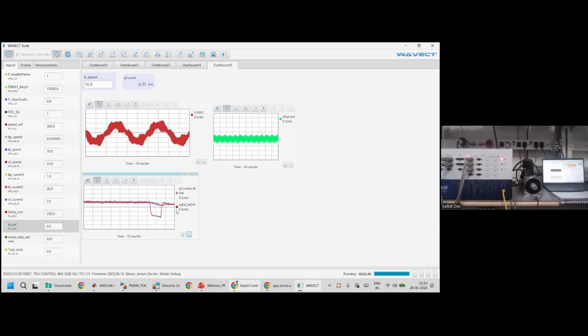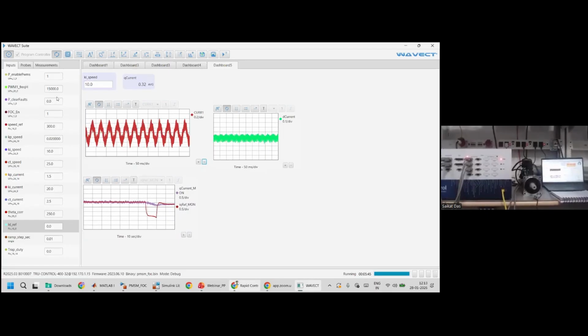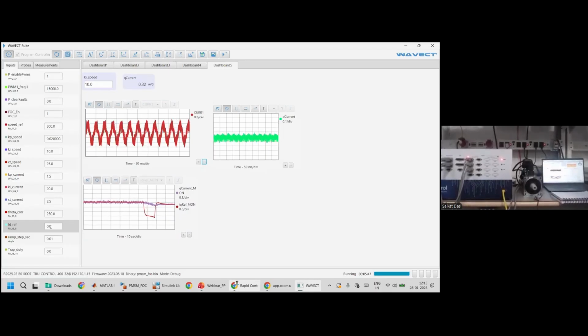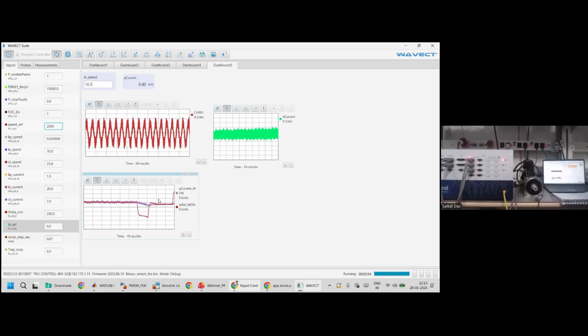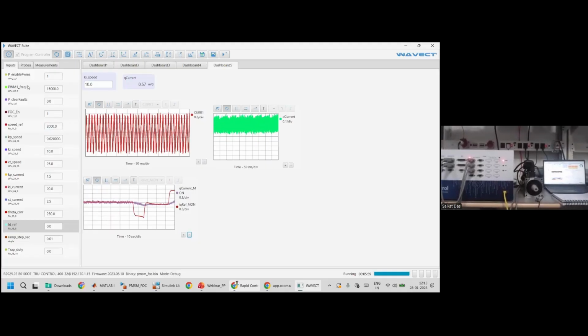Now, let's say some loop is going out of control, so directly by using this input parameter, you can tune it. Or if you want to go back to your MATLAB model and modify your control logic, what you can do, you can directly move on to your MATLAB model, do the modification, generate the code again, and come back to the control loops.